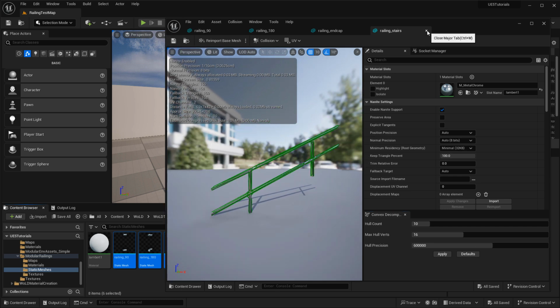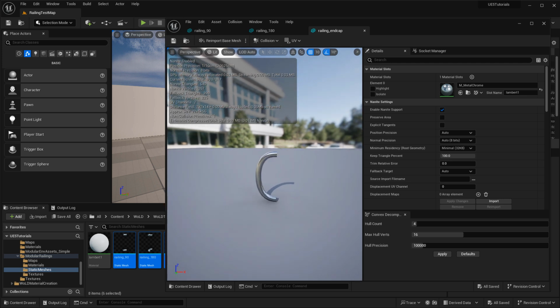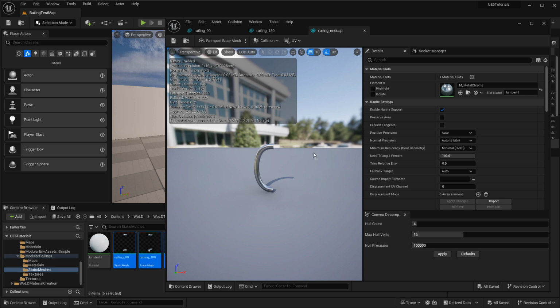Let's go ahead, save. So you can see how quickly you can create collisions without having to create your own custom collisions out of Maya, which you could, but since we have this capability inside UE5, we might as well use it. And if you need something a little more specific, maybe less amount of holes, and you just want to have full control over your collision holes and how you create them, then you should create them inside Maya and then export them along with your mesh. But that's for another tutorial and for another how-to.